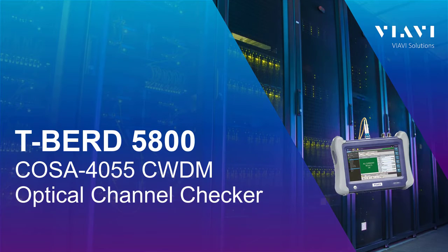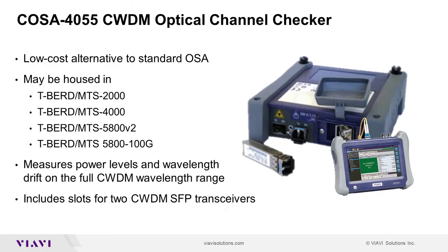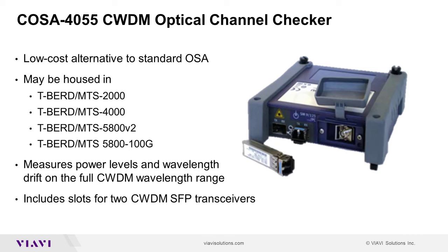Viavi's COSA 4055 module, or COSA, is a CWDM analyzer module for the T-Bird or MTS 2000, 4000, or 5800 test set. The module is used to monitor a live CWDM network and display active wavelengths, channel spacing, and power levels. It can also measure wavelength drift and other statistics over time.